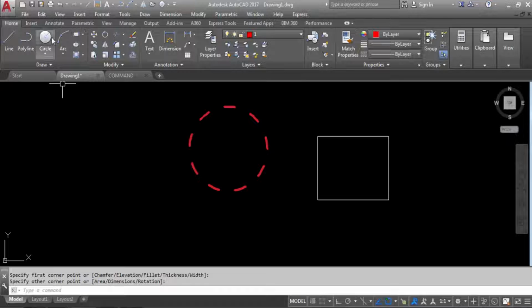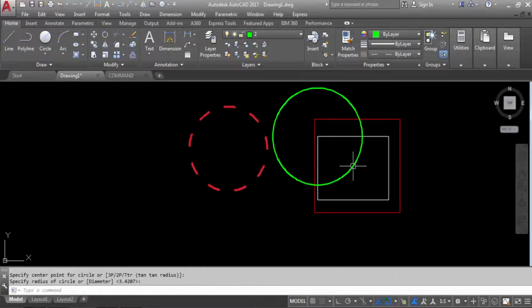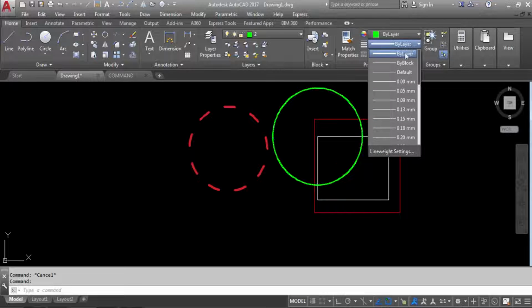So next I will discuss this. Here are all the layers. Suppose I want only the wall layer. In that case, I can turn off all layers and copy only the wall layer from here. I'll show you. Go to the layer properties manager, or you can simply select all and turn off all layers.